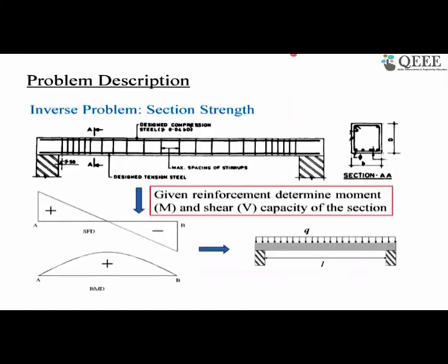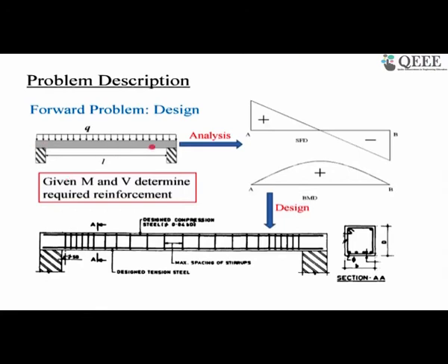Now if you go back to this slide, in a simply supported beam, shear force is maximum at the support and bending moment is maximum at the middle. Therefore bending stress will be maximum at the middle, and if you go towards the support, your bending moment is 0, meaning bending stress is also 0. Whereas shear force is 0 at the middle, therefore your shear stress is 0 for this loading condition. If you go towards the support, your shear force is maximum, therefore shear stress is maximum. So we observe the inclined crack at the support because it is generated primarily by shear stress, and at the middle your shear stress is 0 and bending is maximum, so you get a crack which is governed by bending stress.